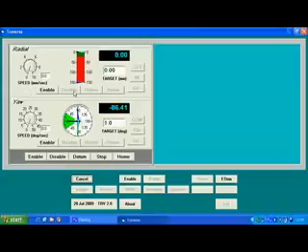You'll notice also these buttons here. Enable will enable the motors so that we can then start moving the actuator. There's a separate enable button for the two axes. If you want to do them both together, you've got a button down here, and again these buttons are repeated down at the bottom. So if we just look at the radial axis first, we can click the enable button, and we'll see that the disable button, the datum button and the home button become visible.